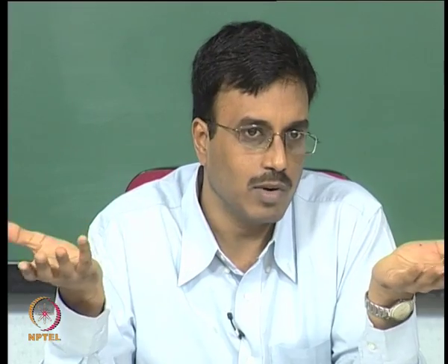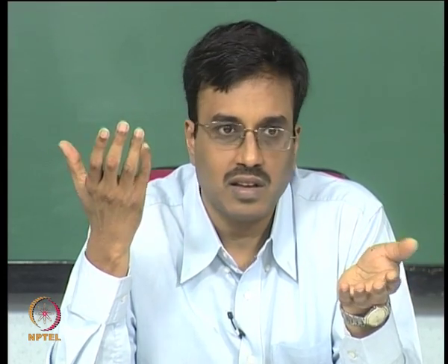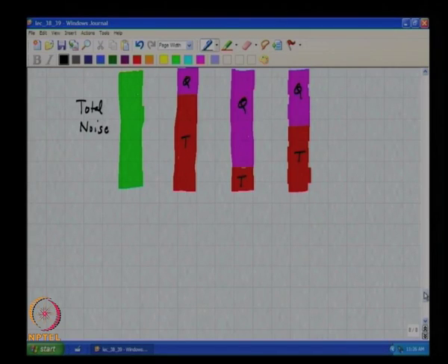Largely thermal noise, right, because if you choose the opposite, then the power dissipation is unnecessarily large, whereas it is very easy to get rid of quantization noise by simply changing parameters of the noise transfer function. So, you always want to make sure that the thermal noise dominates the input-referred noise of the quantizer of the modulator.